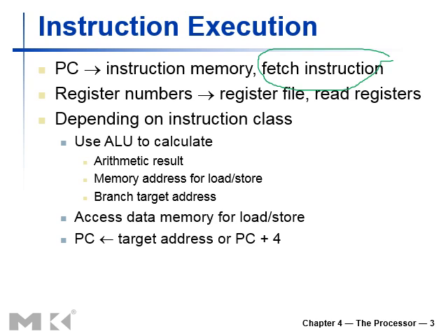Afterwards, we're going to read the operands, and we're going to see where those operands are basically kept. So we've got a register file that contains the operands, either the source or destination or target operand, depending upon the operation which we are performing. So we have to read those registers, and for reading, we have to access the register file.